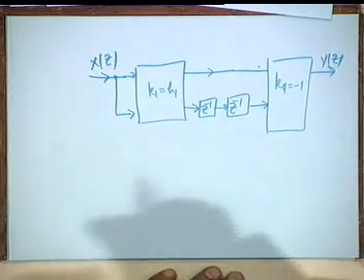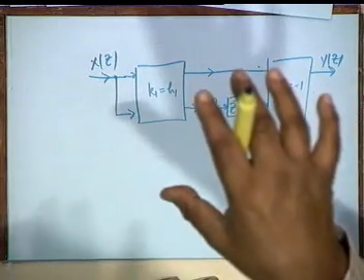So, we have been able to complete all the 4 cases, and linear phase, it will use the same number of multipliers as direct canonic structure, approximately half the number of multipliers if a lattice can be realized with a single multiplier. Okay? If a lattice can be realized with a single multiplier, then the structure will also be canonic.